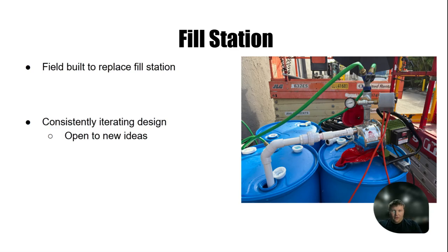That drum is full of glycol, and then as we put glycol into the system, it fills, and this drains out of the tank, this drum. And we have to be mindful. I don't have any float switch on it, so you have to constantly fill it. There's a check valve in the bottom of this that prevents draining back into the drum in the event that this fill pump turns off.